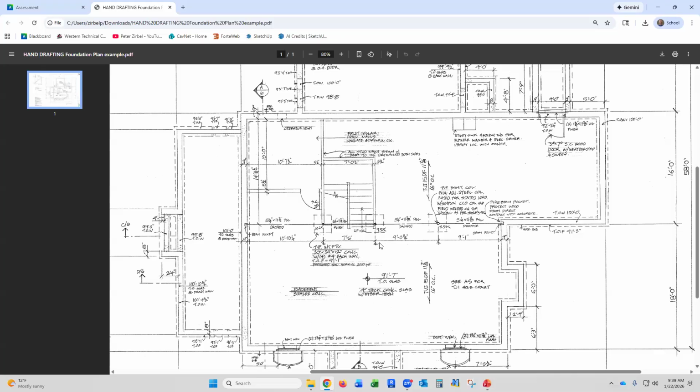And I did exactly what I showed you. We just did the interior footing sizing. I did exactly what I showed you when I sized these footings. So I sized the worst case one. I sized the one for the 10.2 kips. So I figured out which one had the worst kips, but then I didn't make these footings smaller size, right? I figured out the worst case, which was 30 inches by 30 inches by 12 with number four each way. Everybody knows what number 4 is, right? Those little steel rebars. Top of footing was at an elevation of 91.1.